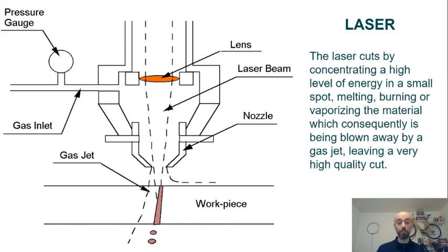And even if you don't damage the lens, that is actually something you don't want to do. Usually lenses are pretty expensive. But even if you don't damage the lens, you definitely lose power. So we want to keep the lens cold, we want to keep it clean, and a constant flow of air is the easier way.